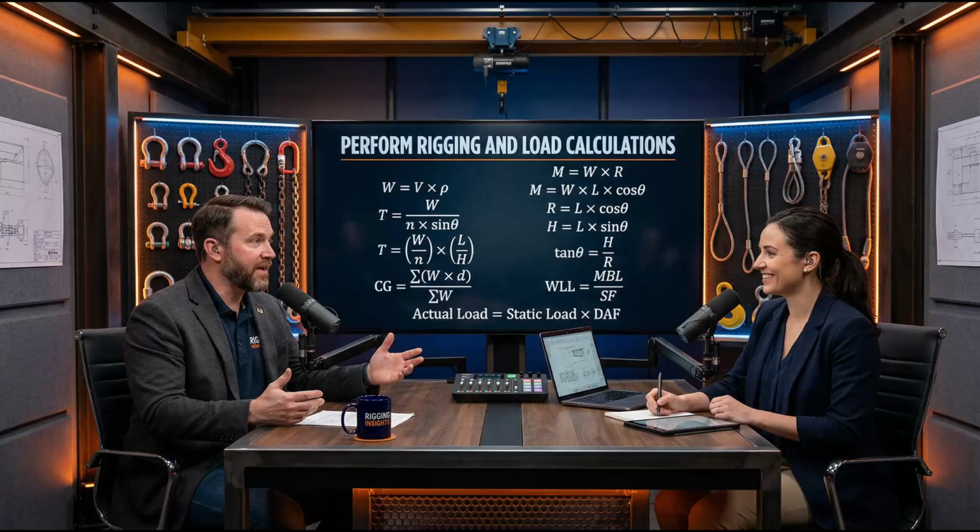This concept requires some vivid visualization for our listeners. Imagine a thick, incredibly stiff wire rope sling, maybe an inch in diameter. Okay, pretty thick cable. Now imagine taking that stiff wire rope and forcing it to bend sharply around a very narrow piece of metal, like a tiny shackle pin or the jagged edge of an I-beam. Doesn't want to bend that way. No, it doesn't. When you force a braided steel cable to make a tight radius turn, you generate devastating internal stresses within the rope itself.